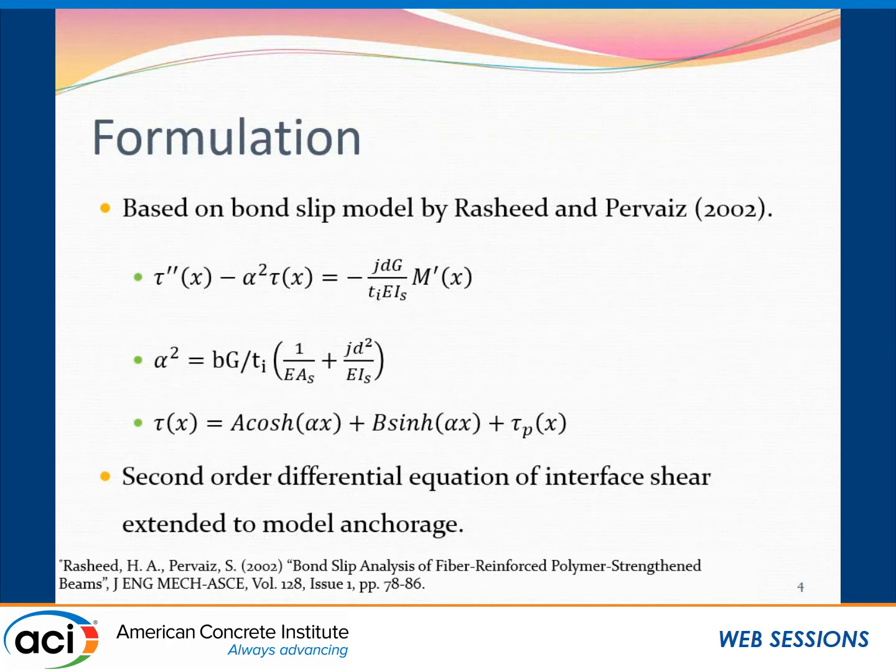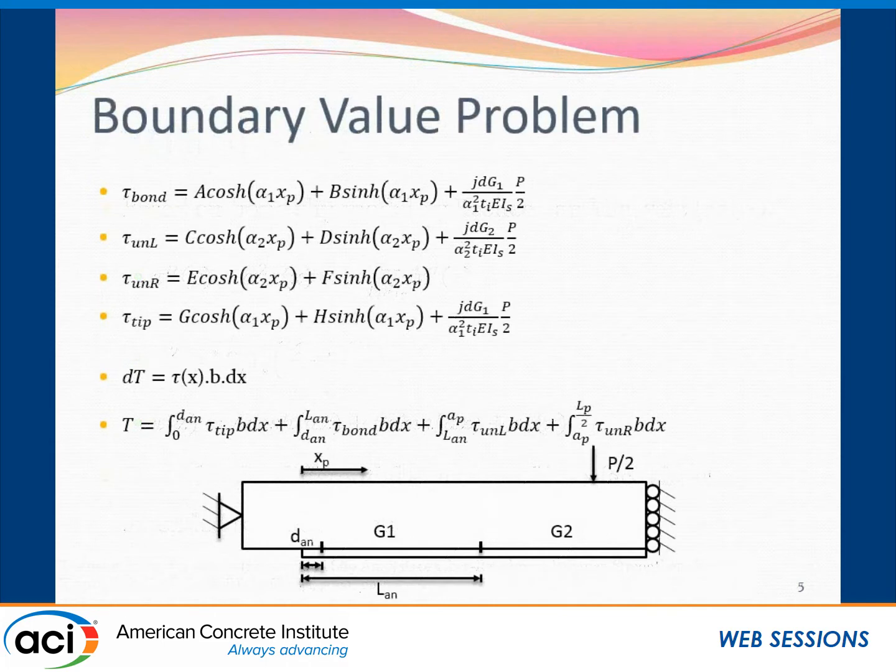Our model was based on the bond slip model developed by Rasheed and Pervez in 2002. Here I show the differential equation that was developed at that time, and this models the shear interface between the FRP plate and the concrete beam. This is the differential equation, and this is the solution for the differential equation. What we did is extend this model to model anchorage in concrete beams, which is on the next slide.